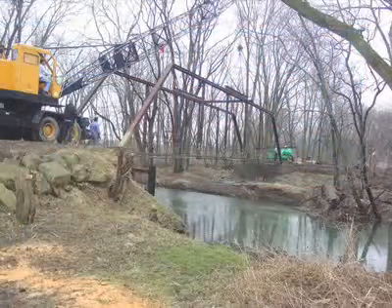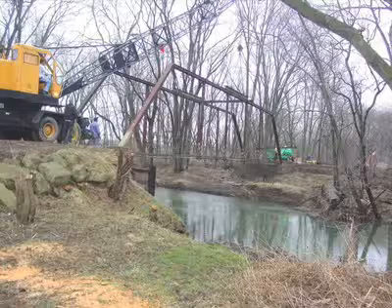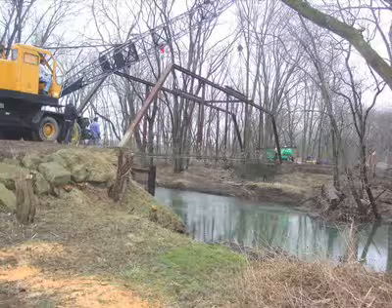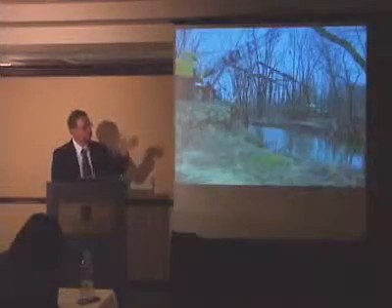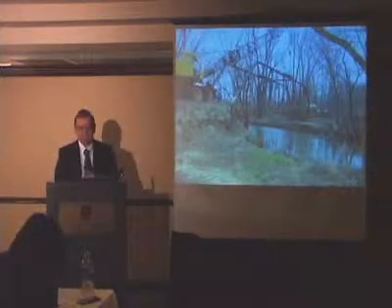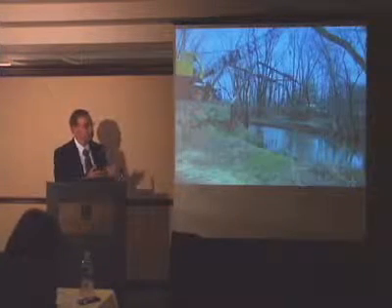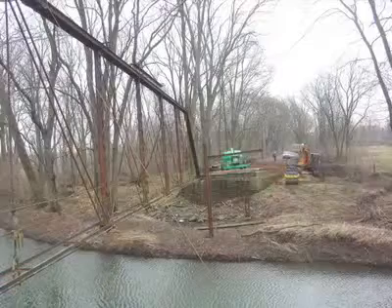The reason the bridge was removed is the abutments were in such bad shape that the specifications called for the bridge to be removed from the abutments, set on the approaches, rehabbed, painted, and left on the approaches. New abutments were supposed to be built, and then the trusses were put back in place, as one unit, of course. But it was easier and cheaper to take the bridge clear apart into all the components and take it back to the shop,